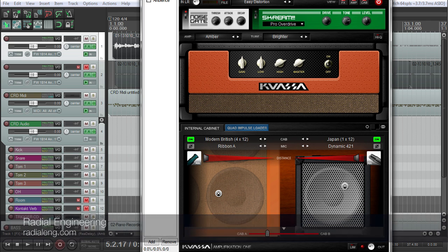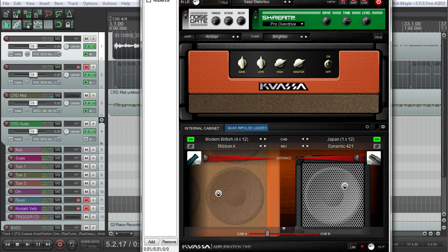The other way is if you have an interface that actually has a specific instrument or guitar or high Z input that essentially will work just like a direct input box or a DI box. It already has the transformers inside to do the impedance matching to make everything work, and so you get the right level, and it has the noise rejection, and everything is cool.